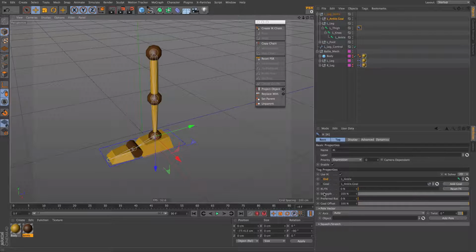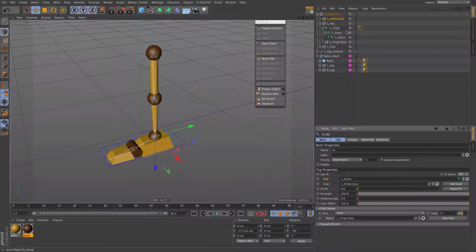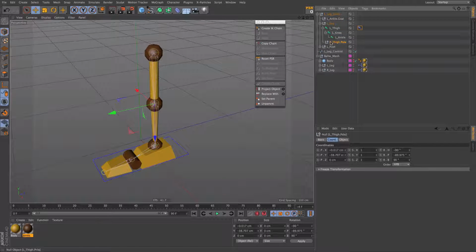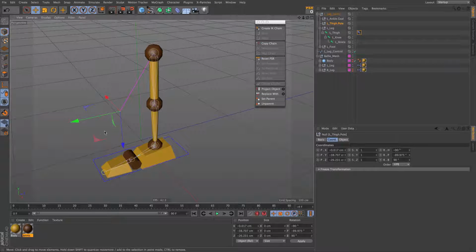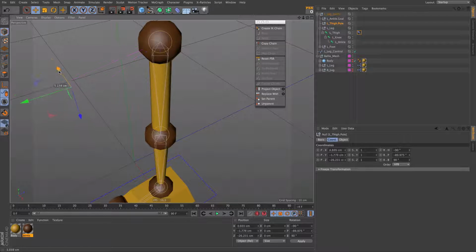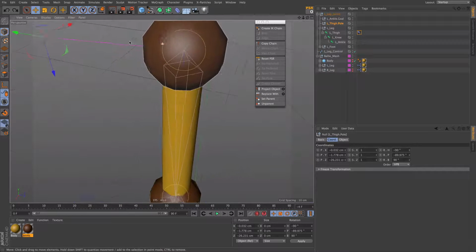It will control the banking of the whole IK chain. So let's make our pole, and you can see the joints already rotated somewhat, and it made a new null, which is our pole vector. Let's bring it out, bring it forward and up. So now you can see it controlling the banking of the chain, and it's aiming with its -x.